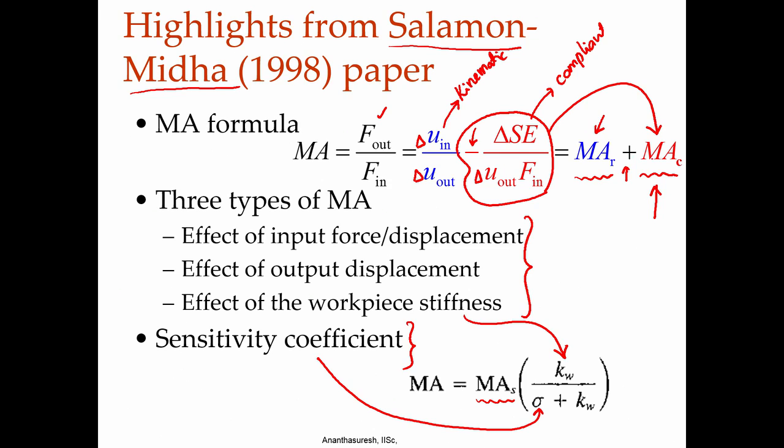So, from the viewpoint of mechanical advantage, there is actually a disadvantage for compliant mechanisms. That is clear because part of the input force and hence energy is used to deform the mechanism. So, there is like a cut taken here as compared to rigid body linkages, and hence both mechanical efficiency as well as advantage are affected.